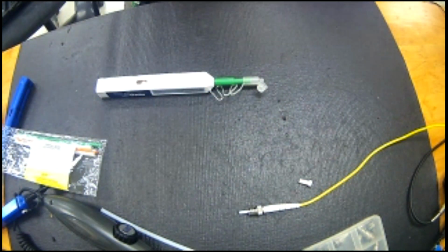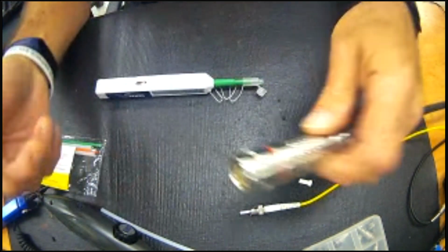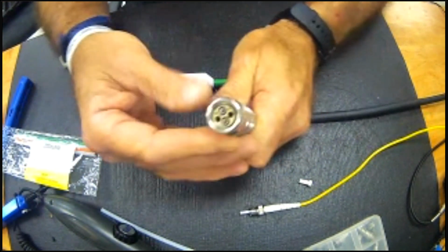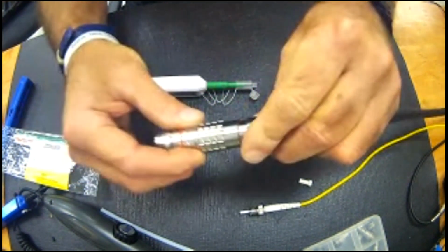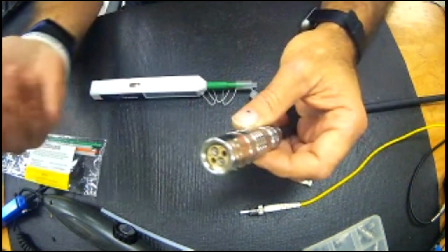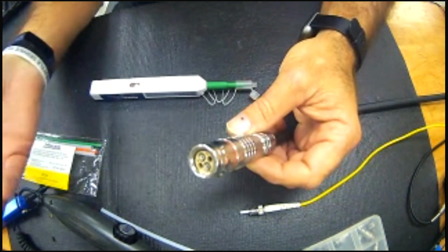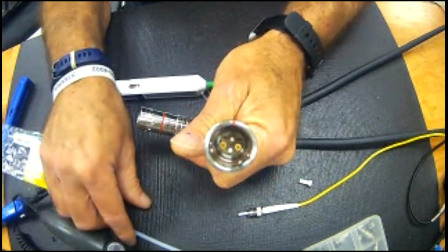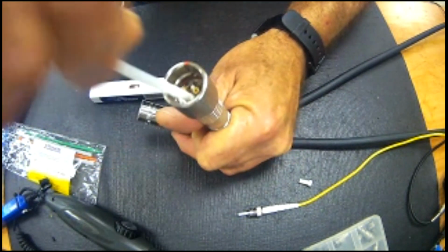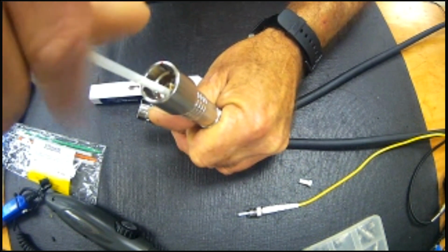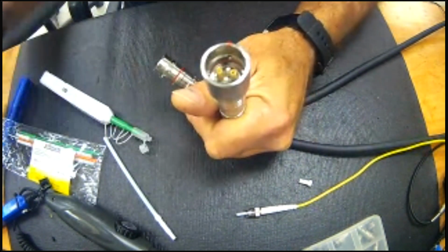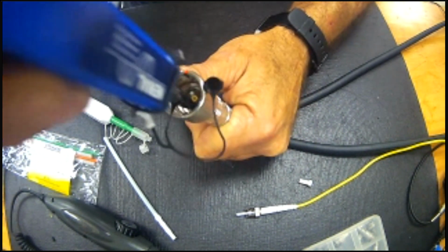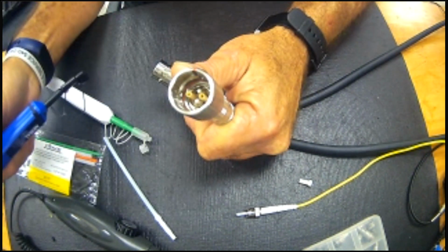So let's move to cleaning a SMPTE, a LIMO connector. The boy has the alignment sleeves, or the plug, the camera end. Just remember, it's the opposite of triax, and you'll get it right all the time. The girl, the jack, has exposed contacts. Reaching inside to clean those with a pen is very, very simple. Simply align it over the top of it and snap.